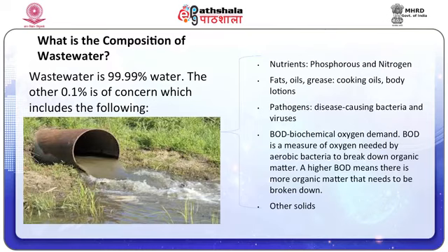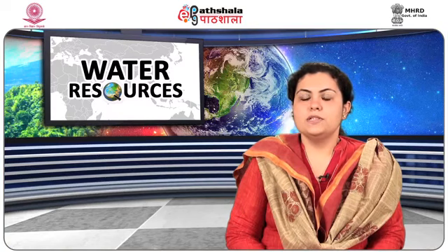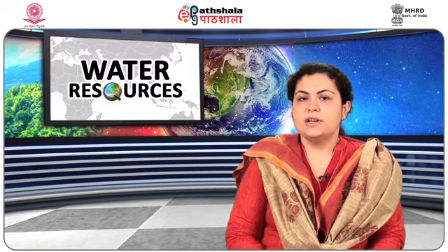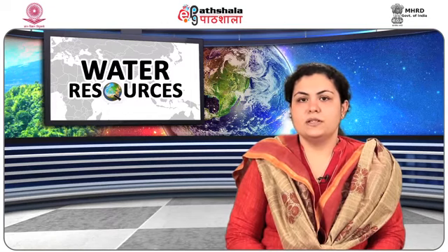Fourth, BOD, biochemical oxygen demand. BOD is a measure of oxygen needed by aerobic bacteria to break down organic matter. A higher BOD means there is more organic matter that needs to be broken down. Fifth, other solids. On analyzing the composition of water, it has been found that of the total solids, 50% is dissolved and the rest 50% is suspended solids.